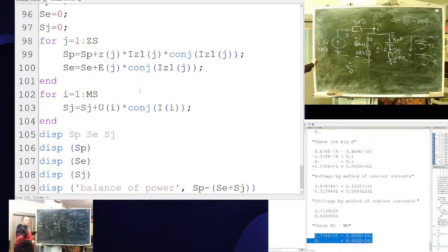Power here, assume it to have an imaginary part. The real physics is that there is an active part, heat or mechanical torque, and part of the energy is reactive: the capacitor charges, discharges, charges, discharges. It's a kind of back and forward wobbling energy. To reflect this imaginary part, reactive power.